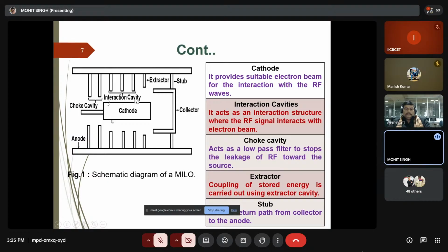They are generating the current, and that current is forming a path with this feedback stub. Whenever there is current flow in the anode, they are creating a magnetic field. That is called the self-generated magnetic field, and it is due to the current which is flowing in the anode. Now, the electrons which are trying to reach the anode will be prevented from reaching it.